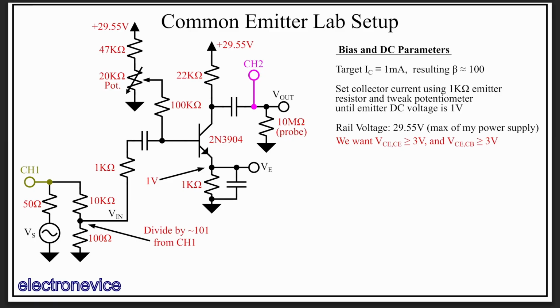We also want to reserve 3 volts for the common base's collector-emitter voltage drop for when we convert this to a cascode, since we want the two circuits to have very similar properties, and we want the same collector resistor and collector current to work for both circuits. We don't need much of a dynamic range above this, as we aren't interested in evaluating the large signal aspects of the cascode. So putting this all together, the voltage drop across RC can be up to 22.55 volts. Setting RC to the standard resistor value of 22K gives us 0.55 volts of excess we can use for the AC signal dynamic range in the cascode circuit.